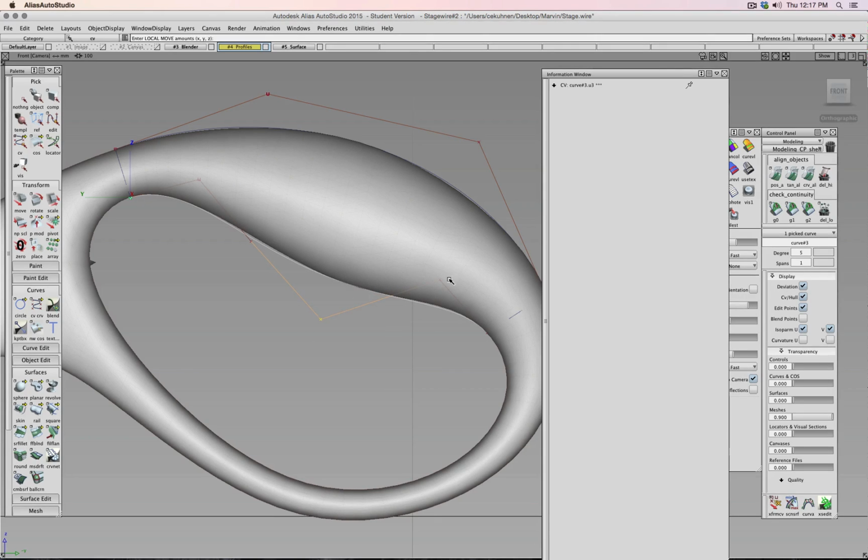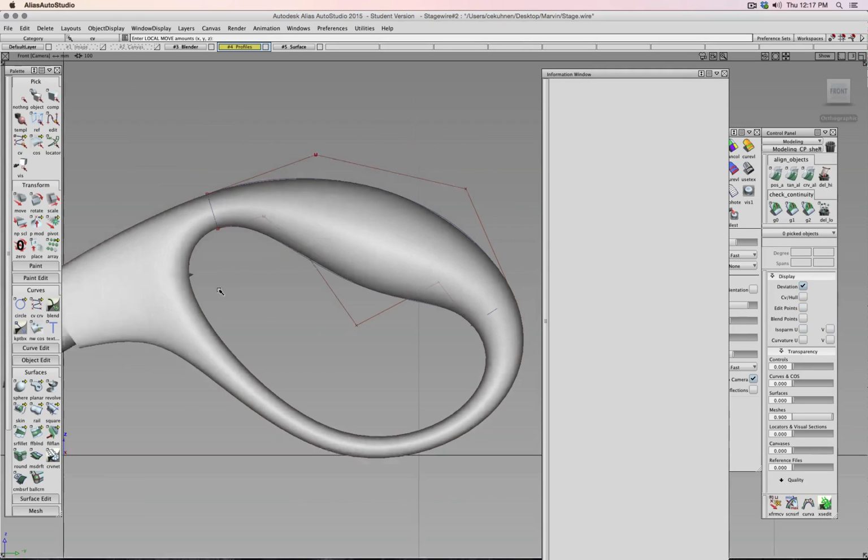So for example, here you see I need more geometry to sculpt this shell. This, for example, I could not do in Blender, to have one curve with less points and here one curve with more points. I would have to be able to add more loop cuts, and then I make my mesh denser. So this is, for example, here right now the advantage of more the mathematical approach of surfacing with curves.